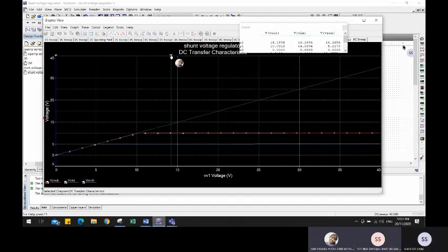If we proceed above 10, the value is still 10 point something and VREF maintains 5.1 until 20. At 20, we still get V out of 10.01, which rounds off to 10.1, and the VREF still maintains 5.1.